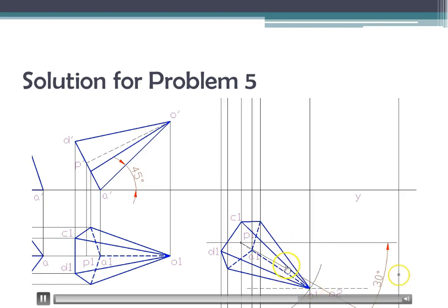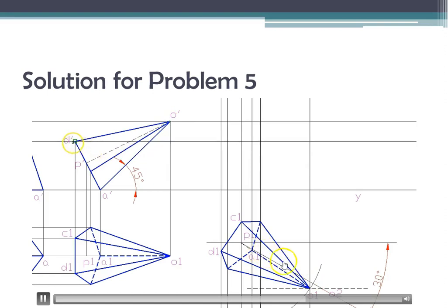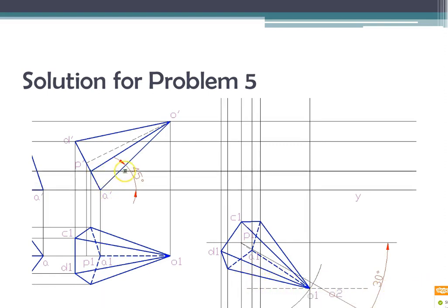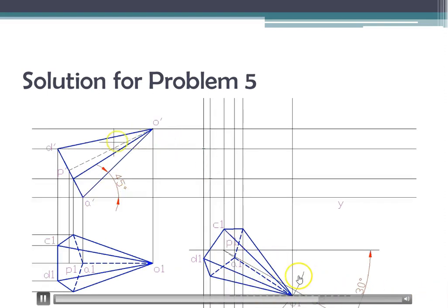In the previous case, the line we had drawn at 30 degrees was itself our view axis location. But here we have positioned the true axis at 30 degrees, and the projection we have found by drawing a locus across the true length at the other end, then marking off the actual projection view of the true length there and projecting it. So the view is slightly tilted towards this side compared to the previous case. That's the difference we get when finally drawing the view.